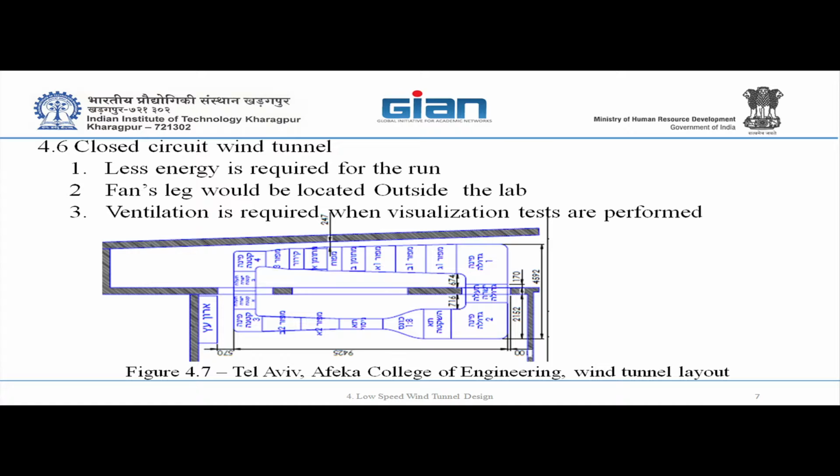That's a rule of thumb, to have the flow there slower than the test section, because then you decrease your losses. If the velocity in the fan was as high as in the test section, your losses would increase significantly. So as a rule of thumb, you look for a fan with twice the cross-section of the test section.